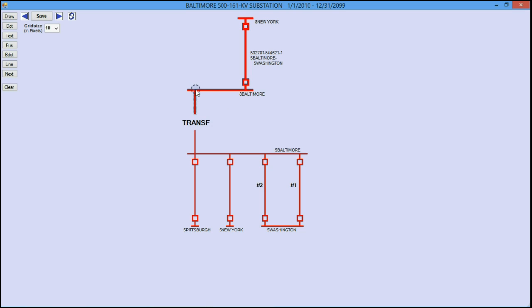See, I can easily position it where the end of that line is connected to that bus. Furthermore, if you want to do a straight line, it helps you position the line such that the line is either perfectly vertical or perfectly horizontal. Now again, I can change this to 1, and you'll see that it's moving very continuously now, but the problem is I might have a little trouble making it a level line at this point. But if I set it at 10, it's easy to make a level line, plus it's very easy to locate it.